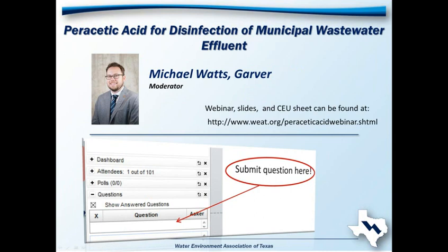When thinking about supplemental disinfection as an alternative, it certainly is an attractive alternative when we think about PAA in front of the UV, because for facilities that are struggling now with high fecal coliform bacteria loads, it's a way to quickly develop a solution for those bacteria in a cost-effective manner that goes in pretty quickly. So from a long-term perspective, tertiary treatment makes a lot of sense in front of UV, but when we're thinking about the role of alternative technologies like peracetic acid, they may be a stopgap of sorts before tertiary treatment is implemented. So I hope that answers question number 2.